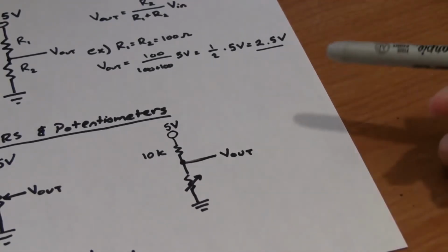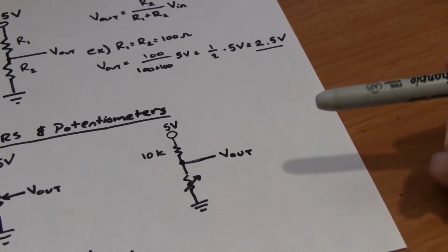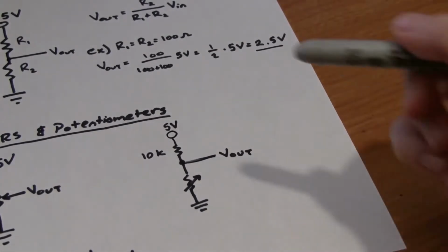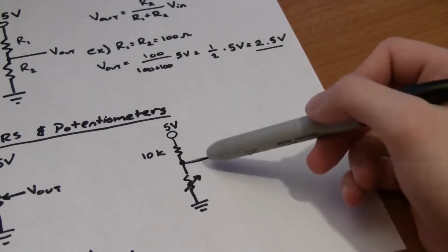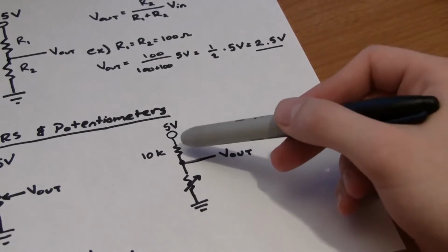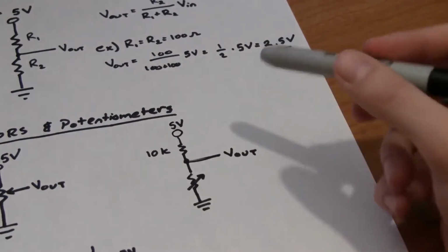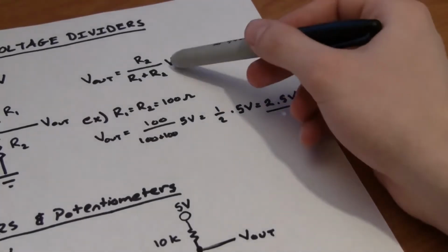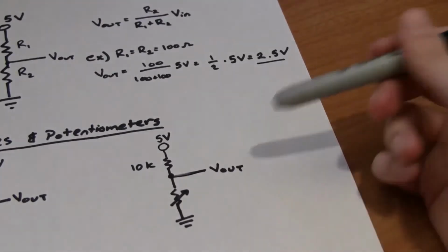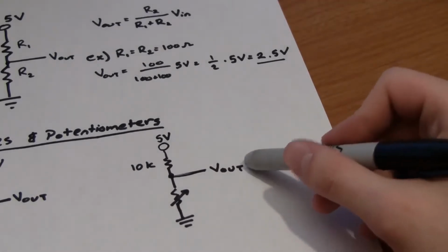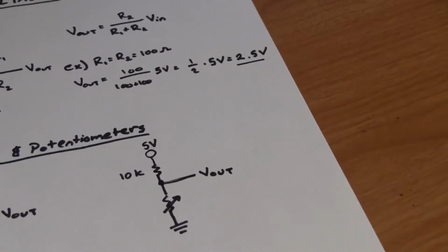Another example is when you want to hook up basically any other kind of sensor to the Arduino. Most sensors work as variable resistors. So if, for example, we have a photodiode, which changes its resistance along with changes in the amount of light in the room, which we represent like that, we can hook that up through a voltage divider circuit. So once again, we'll have 5 volts. We usually use about 10K as the other resistor, and then our variable resistor right here. As the light in the room changes, this resistance varies, which affects the voltage divider equation, and we therefore get a different voltage out. So as the light in the room varies, we get a different voltage out of our line here, which then gets fed into the Arduino's analog inputs, and we can read that value between 0 and 5 and do something interesting as a result. So let's see an example of this in action now.